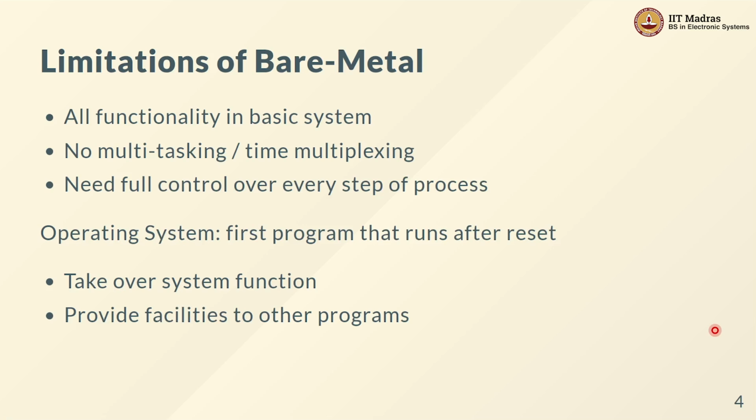You would probably have some kind of a while loop. Even if you go for some kind of a basic operating system, like we considered the FreeRTOS and so on, all that is doing is providing you with some kind of a while loop that basically says, okay, this program will run for a certain amount of time, then stop and hand over to another function. So the functions basically switch from one to the other individually. You have to have the full control over that.